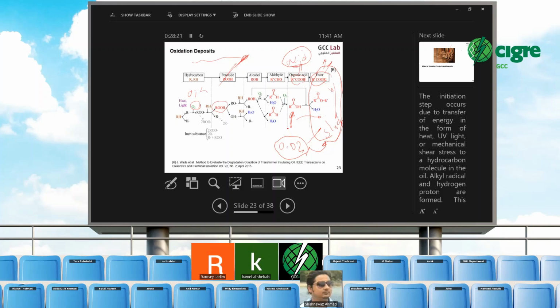So do oil regeneration to remove the acids from the oil. But if you have oxidation deposit, there's no solution. The first solution is rewinding. But our task is to tell you that before the fault, take action now before you get to the problem. So therefore, I think so.